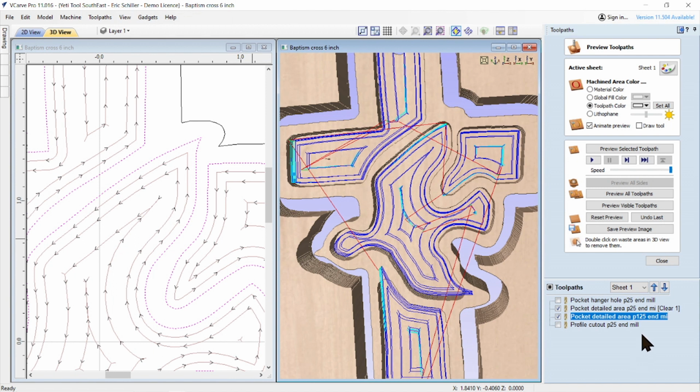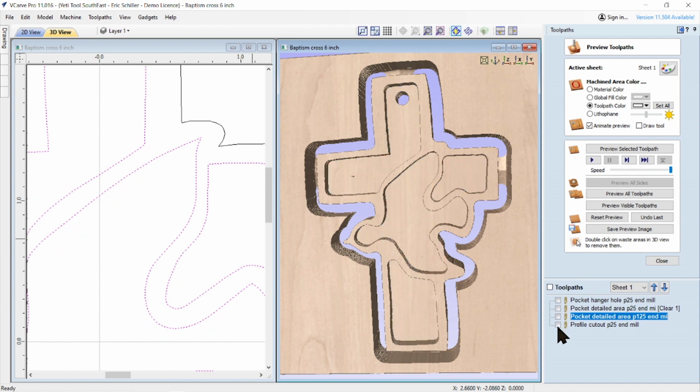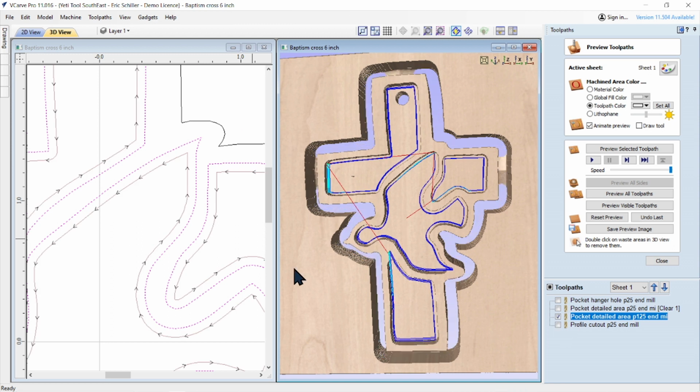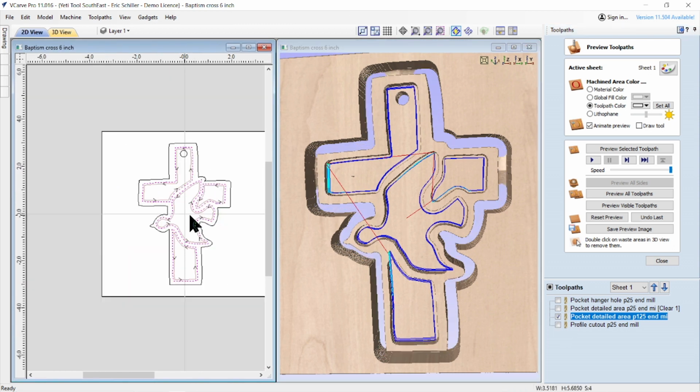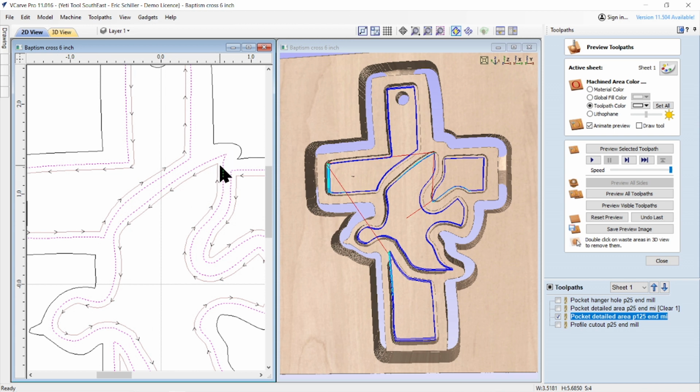And that sounds good. So there's a couple different ways you can do this. Since I have the big tabs on it, it would not be impossible to come in here and just have the smaller 1/8 inch bit come in and just clean up the outside areas of that pocket and to dig deeper into these pointed areas. That would hold.